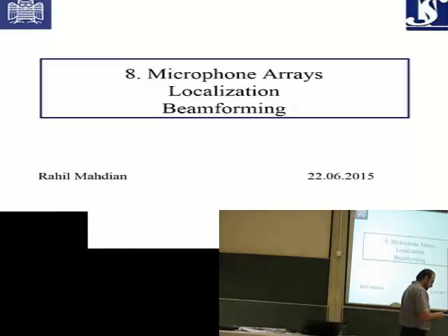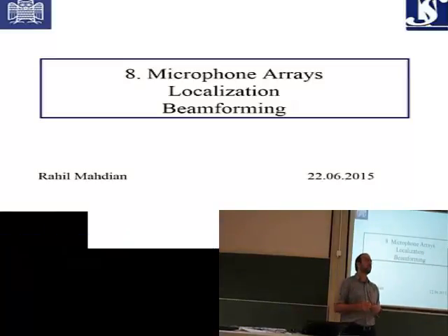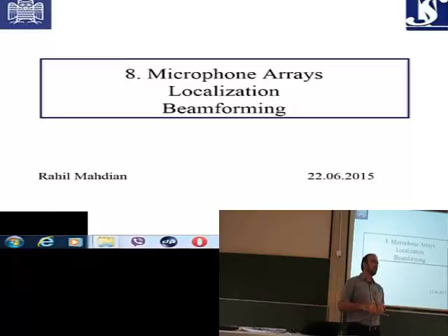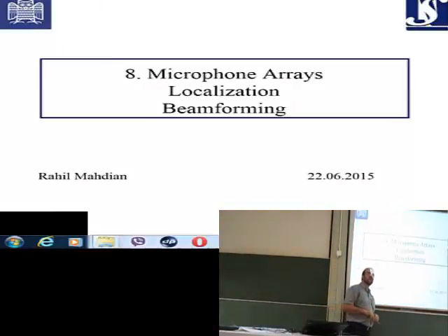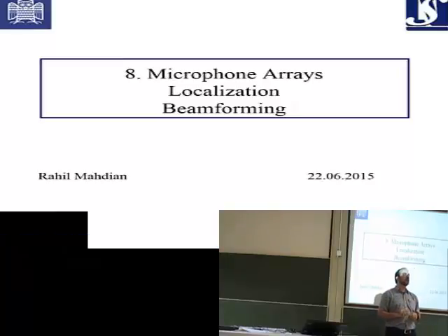But we saw that there is a big problem inside joint time frequency representation, and that was the constant tiling strategy. It means that for the STFT or Gabor, it doesn't matter whether you're observing the signal in the lower frequencies or in the higher frequencies.